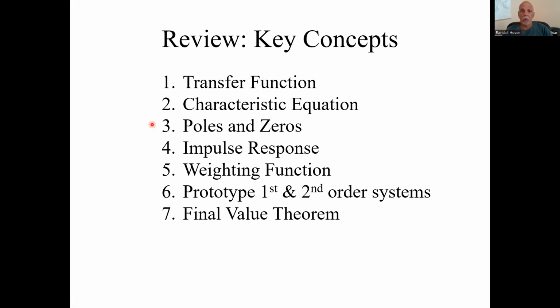The characteristic equation tells you where the poles are, and where the poles are in the complex plane will tell us later many aspects of the dynamic behavior of the system. So will the zeros, which make the numerator of the transfer function go to 0.